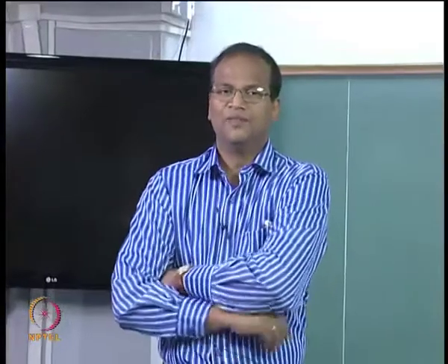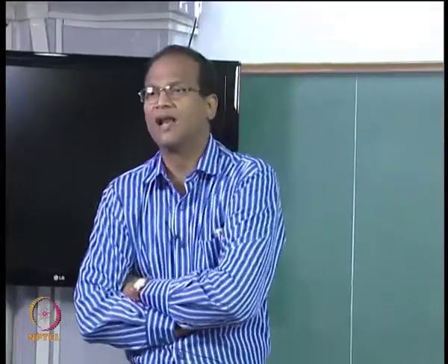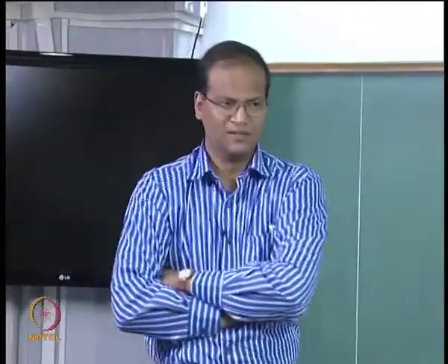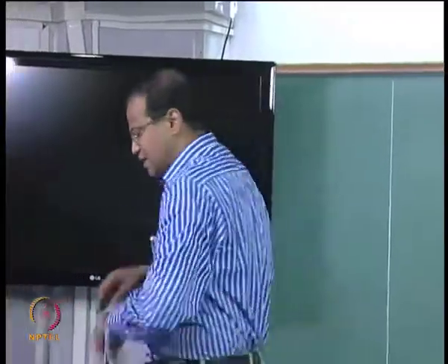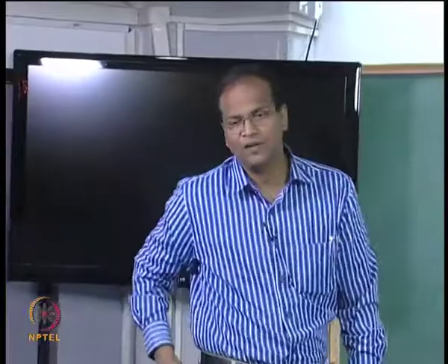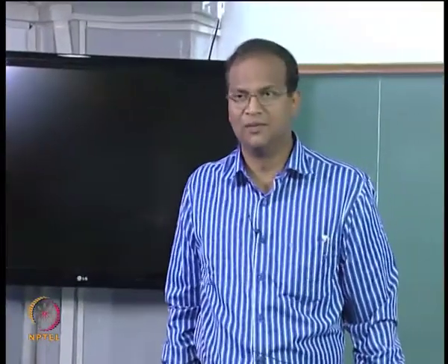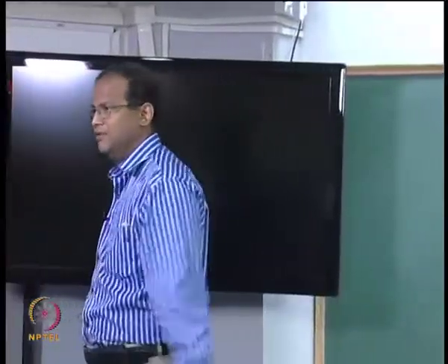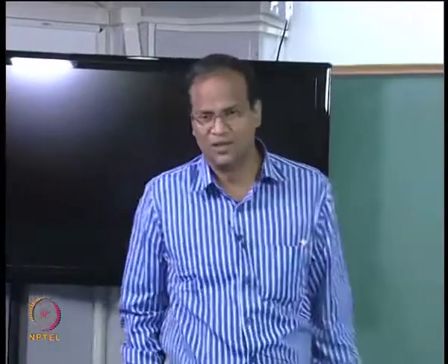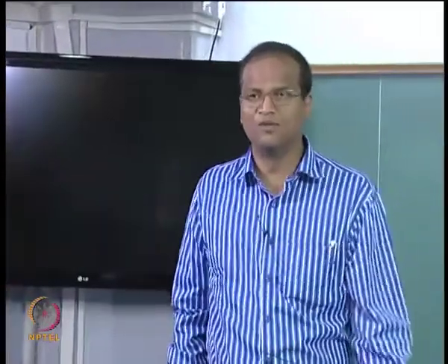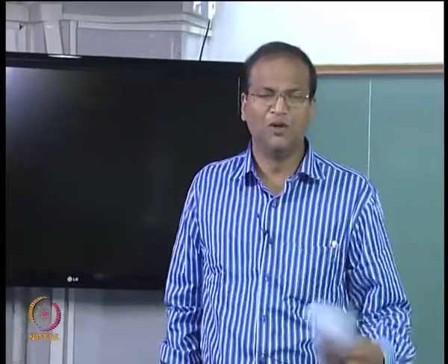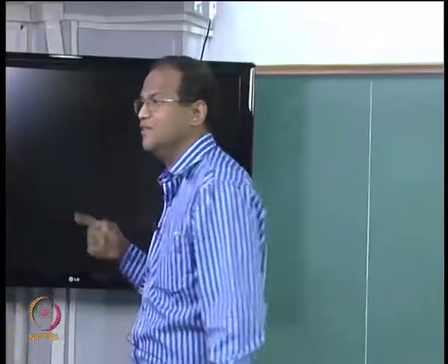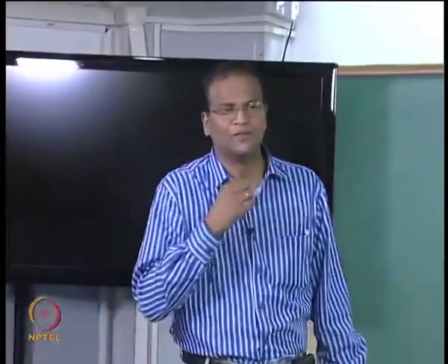And some people have developed techniques between two parallel rectangles, between two perpendicular rectangles, between two coaxial circles, concentric coaxial disks. So people have developed this integration and they have presented the results in the form of charts as well as tables. I did not give you the tables, I have given you the charts. The accuracy is somewhat lower for the charts, but it is okay for this course. If you want to actually solve problems involving radiation, maybe you can use the tables, or you can write the program yourself and subdivide each surface into elemental surfaces and calculate the view factors.